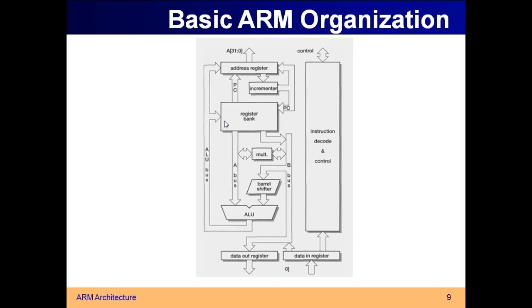That means the program counter will increment on its own, and the program counter is nothing but a pointer. It points to the next instruction that is to be executed. Initially, let us take the program counter at address location 1000. After reading the instruction from 1000, the program counter will automatically increment to 1001. You don't need to increment it. That is how the processor keeps track of each line of instruction.